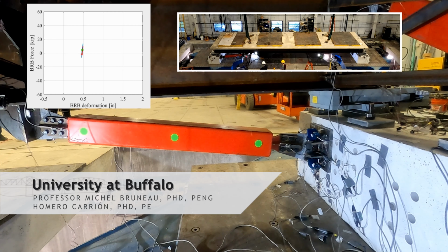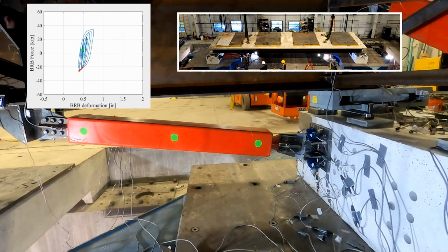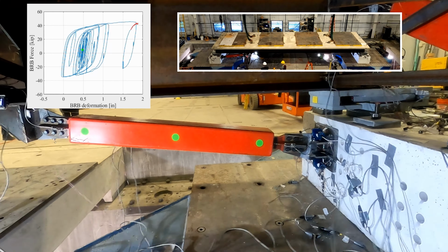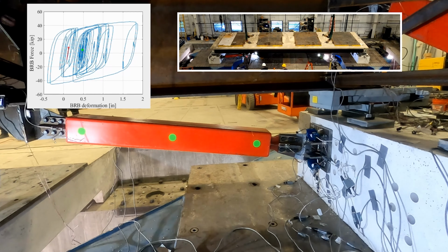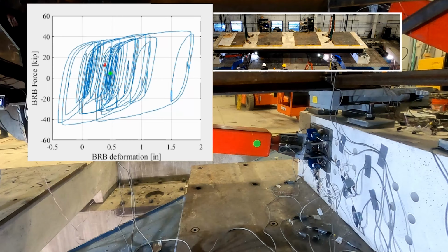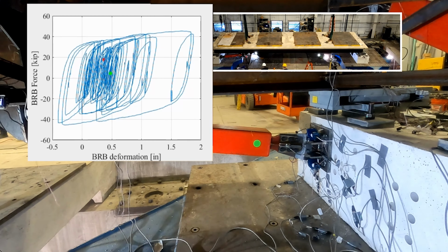areas undamaged. Expanding this concept of energy absorption to a structural element under high-strain cyclic loading, engineers perform testing on actual bridge elements. They do this by pushing back and forth on the element and increasing force until it yields. They then continue the cyclic motion with slight force increases but causing large displacements. This generates hysteresis loops that plot force and displacement.